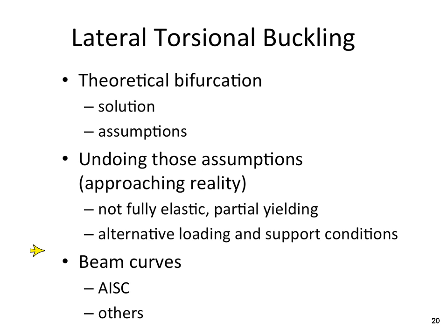Okay. I'm actually going to get into that later in my lecture, but the way you can think about these braces is twofold: one, bracing for twist, and two, bracing for lateral movement. The bracing for twist is the most important one. What you're trying to do is prevent that relative movement from occurring. Now that's not to say that if you could somehow hold on to one portion of the member, maybe the compression flange, and prevent some lateral movement, that because the tension portion is also acting against you, you couldn't improve the situation. But the real crux of the matter is that to provide a good solid brace, you really need to resist twist.